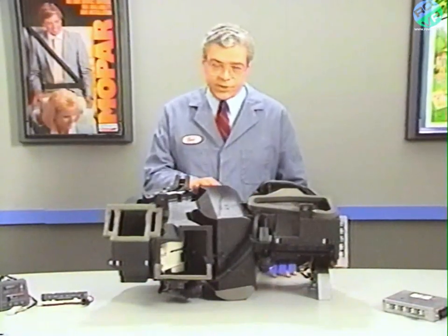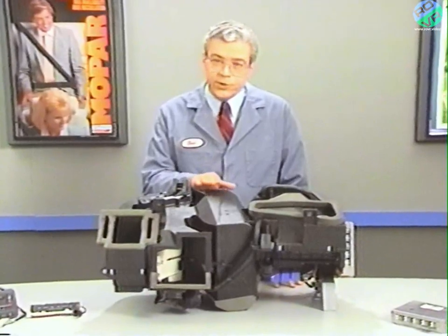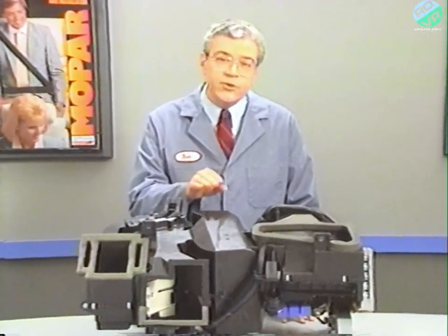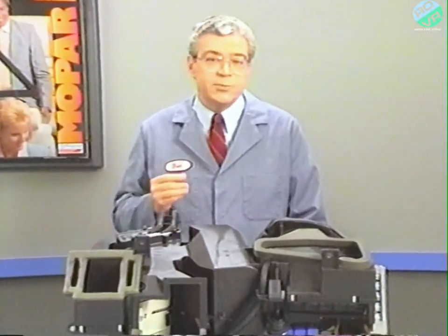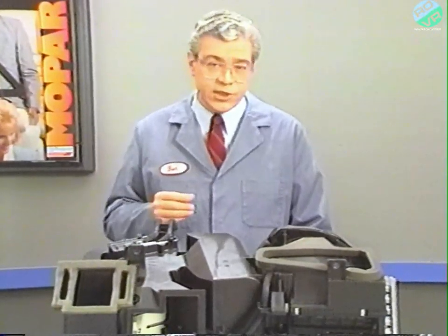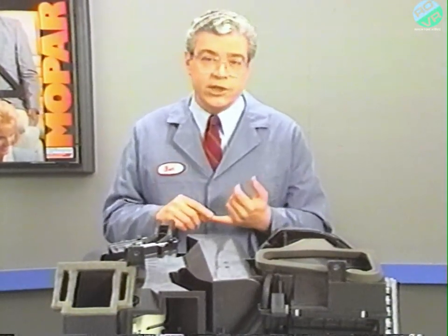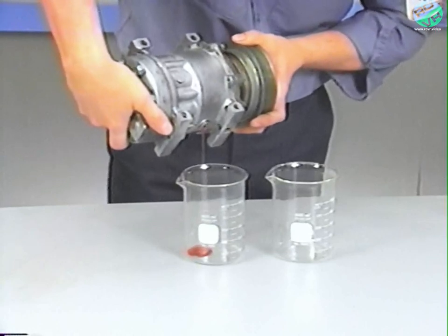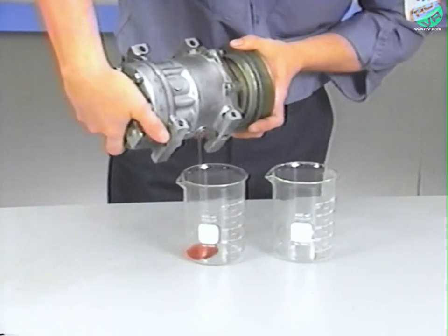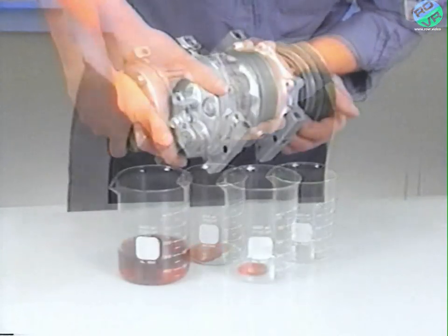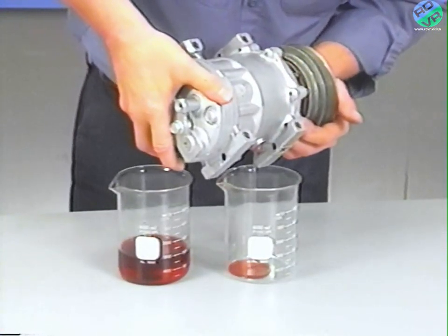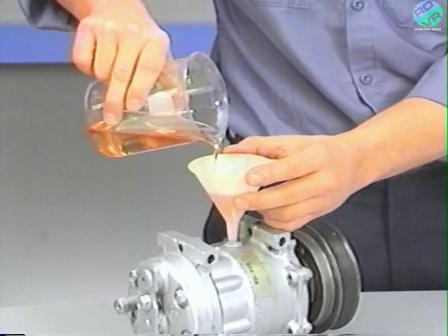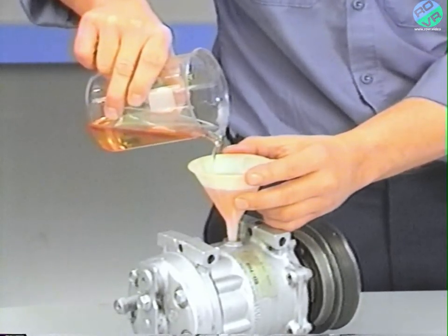The second AC service item concerns keeping the correct amount of refrigerant oil in a system during compressor replacement. Keep in mind that a certain amount of oil will stay in other system components, so installing a replacement compressor that is filled with oil may overload the system. As a result, before installing a new compressor, be sure to measure the amount of oil that was left in the old compressor. If you find that the oil is contaminated, be sure to install the new orifice tube filter described earlier. Then, drain the oil contained in the new compressor and put back into it the same amount of oil that was left in the old compressor. This helps to ensure the amount of refrigerant oil in the system remains the same.